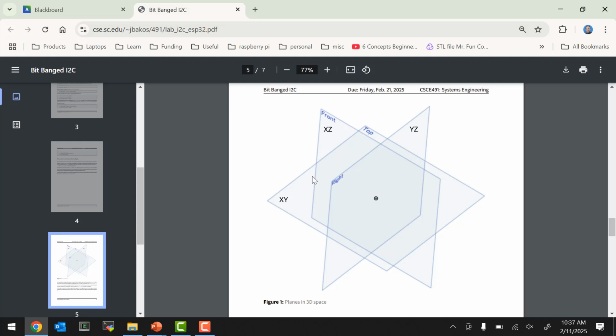Oh yeah, Alex. Sorry, one other thing I almost forgot. Alex is going to walk around and blow the fuse. Yeah, so all ESP32 boards by default have a flash chip on them, which is the flash memory that holds all your code. That flash can either run off of 1.8 volts or 3.3 volts, depending on the ESP32 model. And in our model, the flash can only run off 3.3 volts, but it's configurable by the state of one of the pins at power on time.